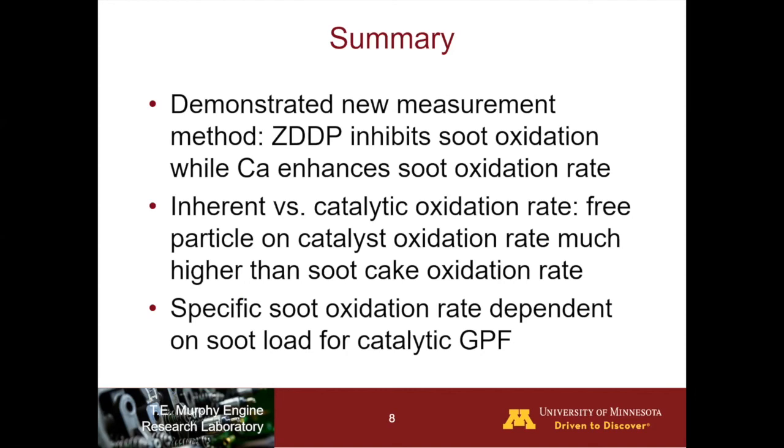And because of that last point, the specific soot oxidation rate in a catalytic GPF is dependent on soot load, where that might not be the case in a non-coated GPF, where the oxidation rate would just be that of its inherent soot cake.